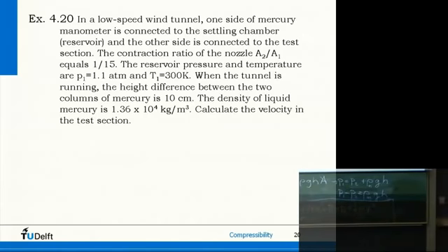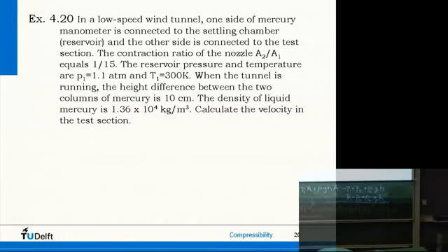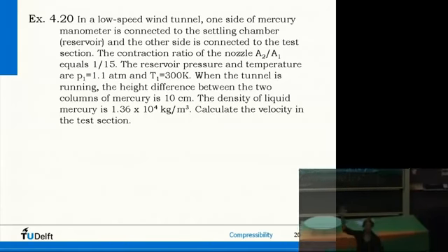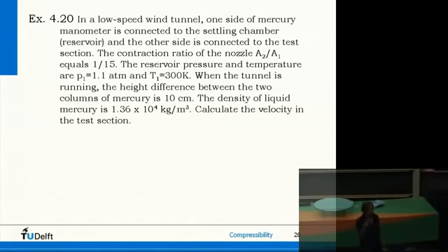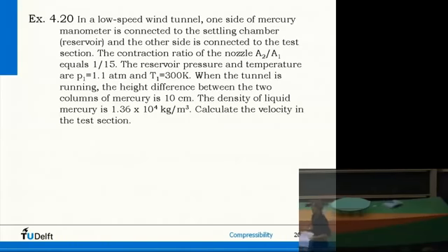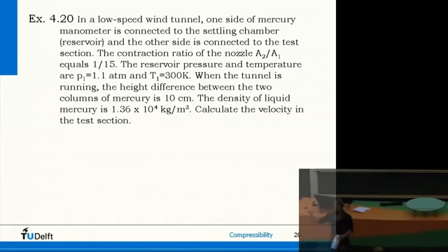And it's maybe a bit misleading. Low-speed subsonic wind tunnels are much different from supersonic wind tunnels. Supersonic wind tunnels work with a huge reservoir under very high pressure, and then the flow is injected through a very strongly converging-diverging nozzle. That's typically not how subsonic wind tunnels work. Usually we have a fan and we pump air around through a much less strongly contracting nozzle. And we don't typically have a large reservoir. It's really flowing through. So the picture I showed you before is how it works.